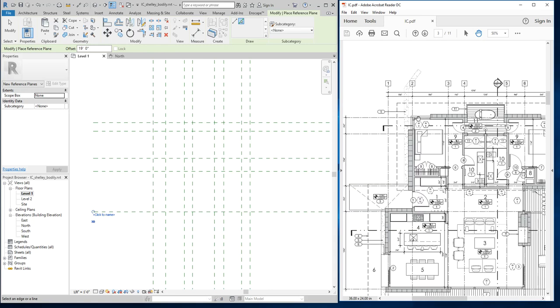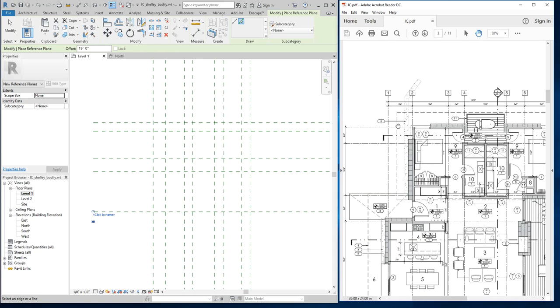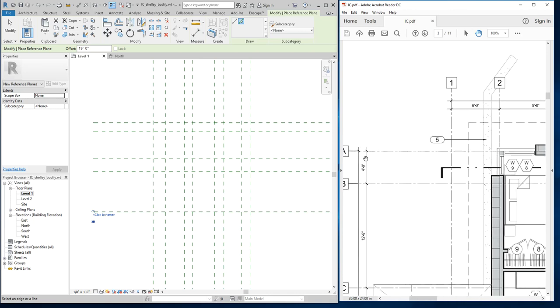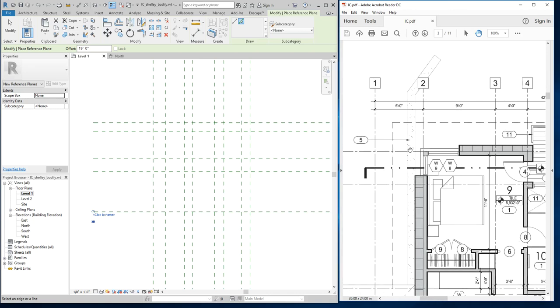And I think I'll probably just kind of start up in this top corner here, where grid line 2 meets grid line A. Okay. There's a window there, but I'm not going to worry about windows just yet. We don't know how to do windows yet. We will in about 2 class periods, but we don't know yet, right? And I'm just going to draw on this line of structure here. Okay, so I'm going to pick just a generic wall type.